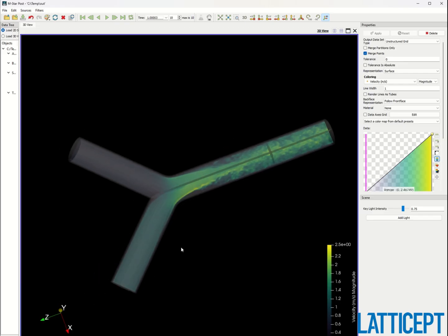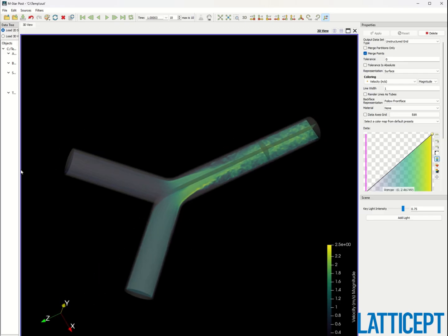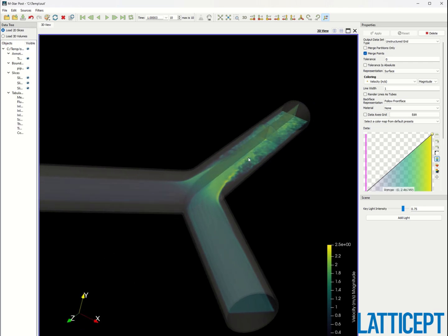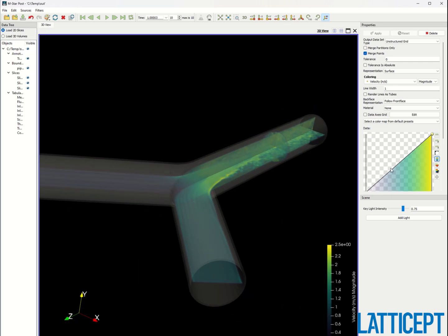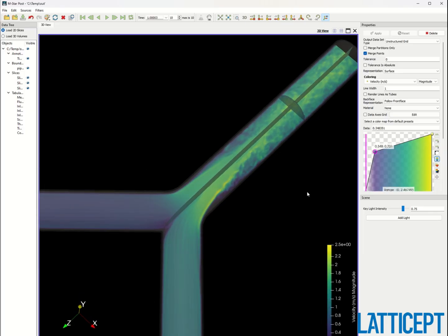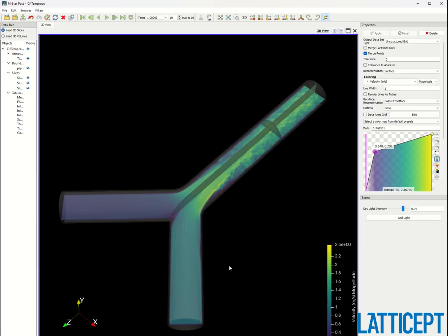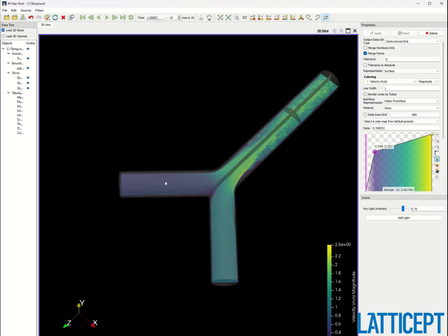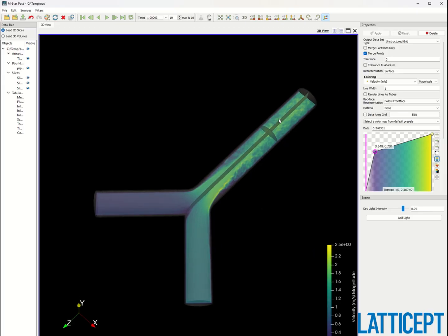Two things. One, you'll notice that it starts off not turbulent, so we probably want to change that. The second thing is, well, that's mostly the main thing. Okay, so in Lattice Boltzmann, we don't have a synthetic turbulent entry point. Okay, so here you see it starts off laminar and ends up being turbulent down here.